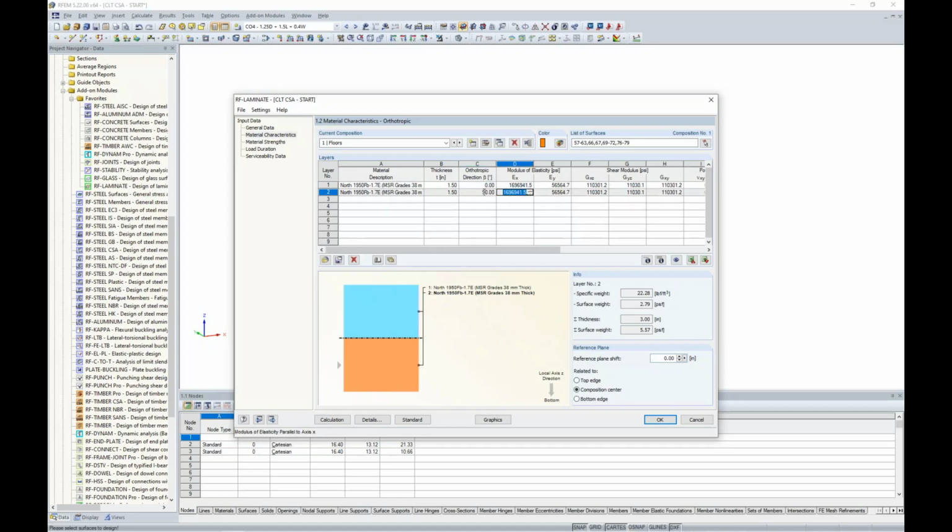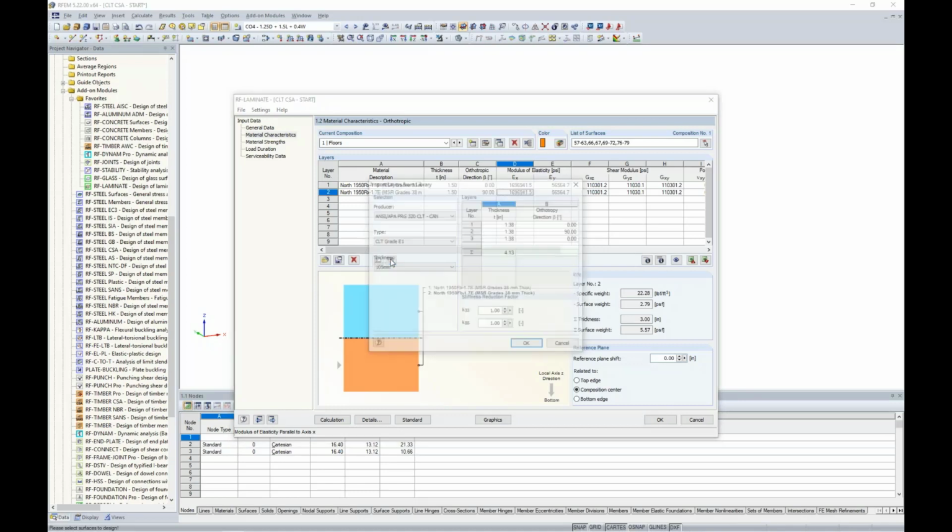from the first layer. Now this is relative to the local x-axis, which we'll get into a little bit later. So once you create your custom layups here, you do have the ability to save them into the library and open them up for a future model. We also have the ability to take advantage of the imported layers from our library already available.